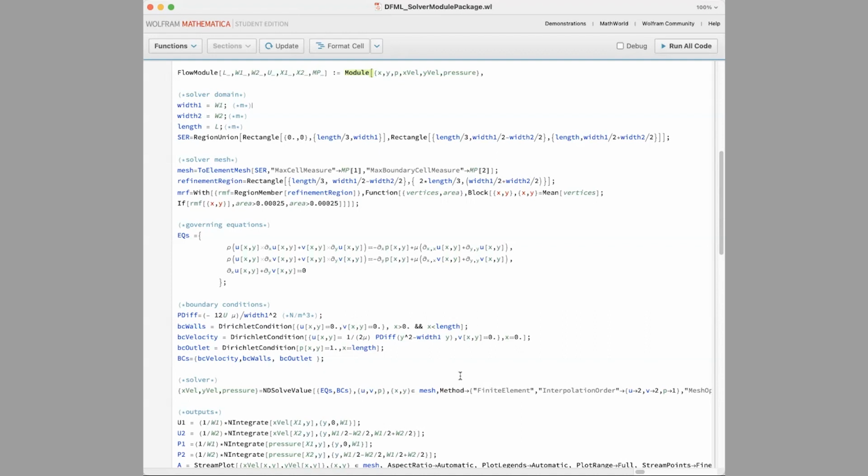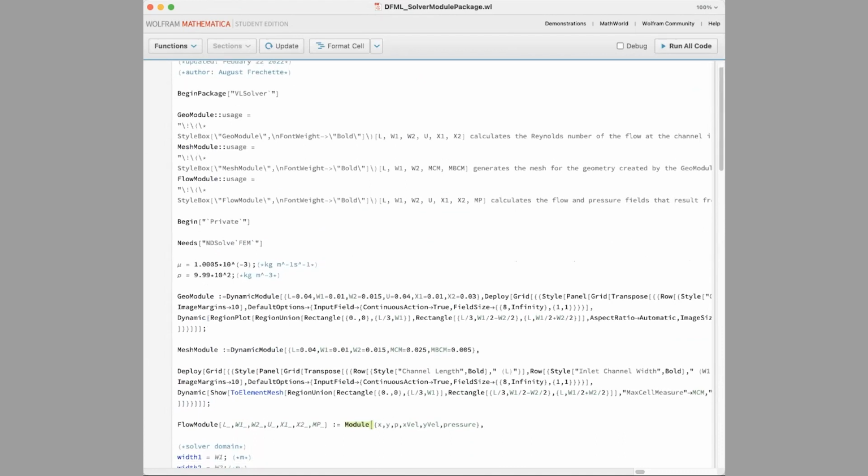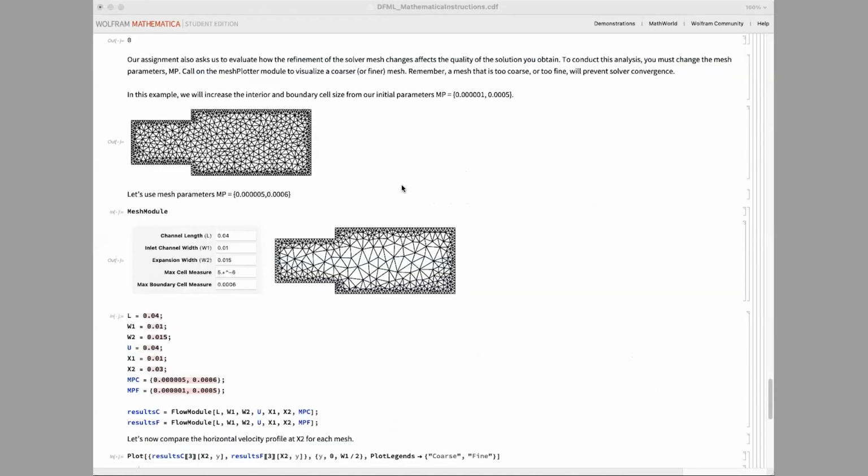If your grid is too coarse, you're not going to capture what's happening inside of your domain. All of your calculations are happening at the intersections, and depending on what kind of mesh you specify, it might be happening along the midpoints too. Let me go back. You can see here we have a lot of calculation points.